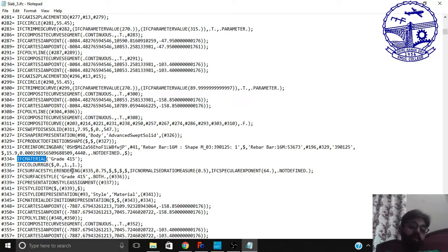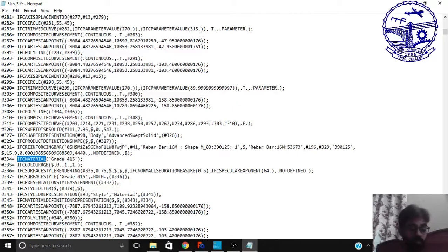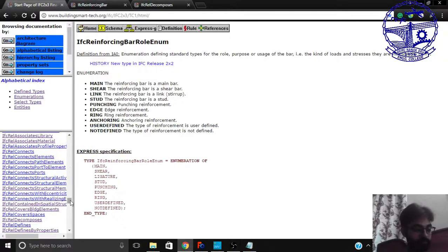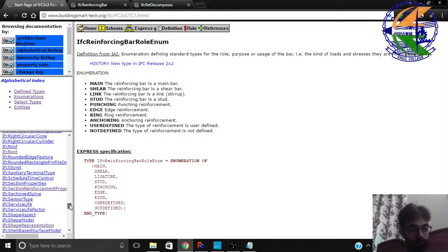But if someone, as a structure engineer, as a mechanical engineer, needs some more minute details, then there are some more detailed things which are defined here, like the IFC rel associates material. So I should just give you a brief overview of that, like the IFC steel properties or the IFC concrete properties. So how does the IFC define that? Let me just show you for the steel.